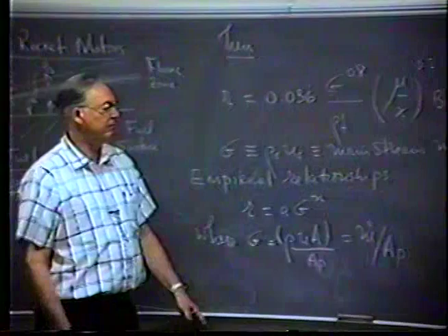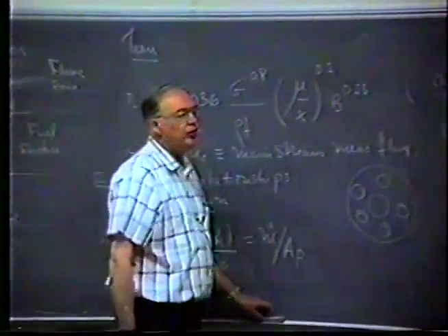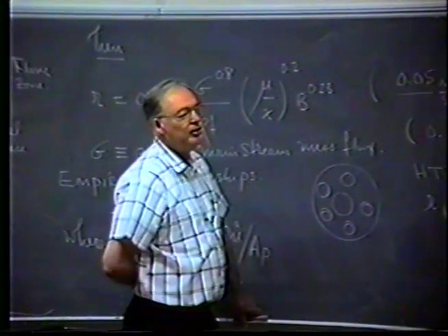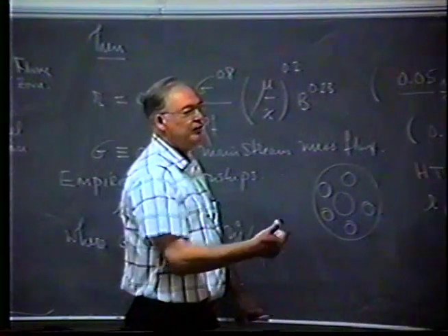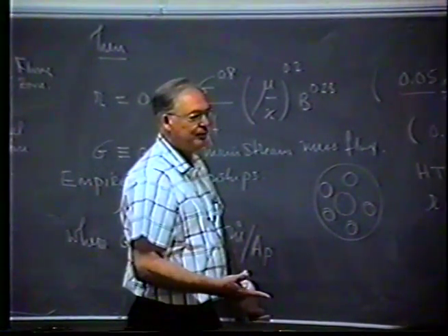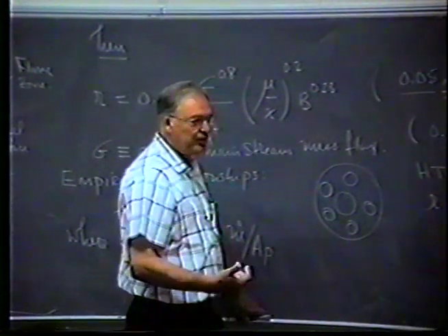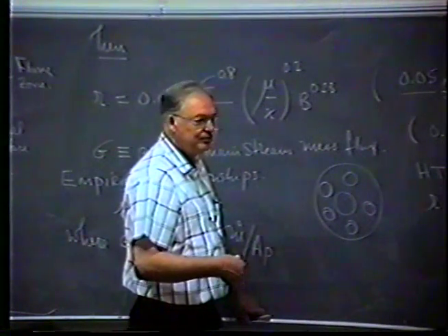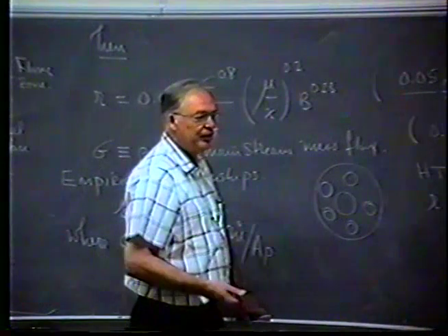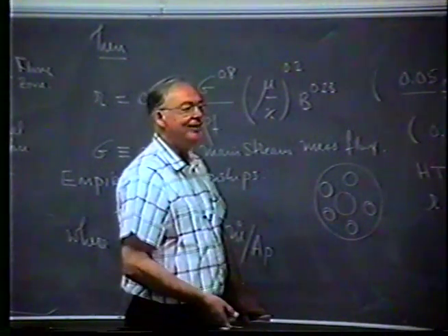Ben? Can you cheat on these hybrid rockets? Cheat? Yeah, and sneak. There's no such word in solid rocketry as cheat. The words you want to remember are deflagration, which is a good thing, and detonation, which is a bad thing. You got those two words? Yeah. Now, you can fix this up so that you can get one or the other. If you cheat, you're going to get detonation. If you don't cheat and you do it right, you get deflagration, which is a nice normal burning rate. Now, Ben, which of those do you want?